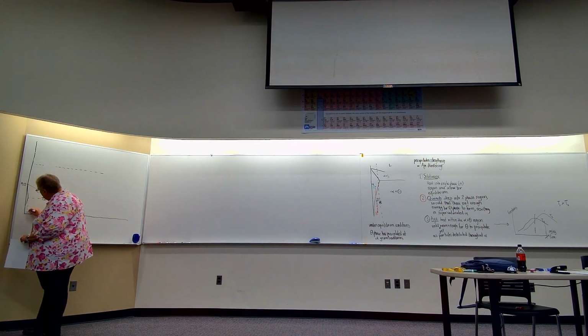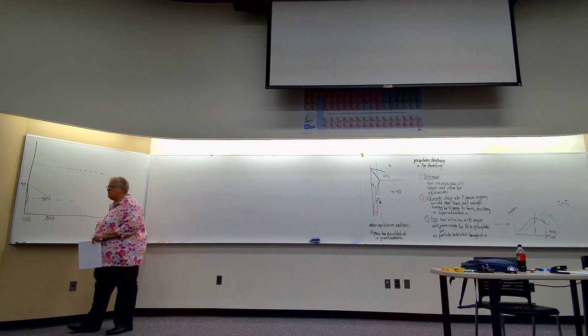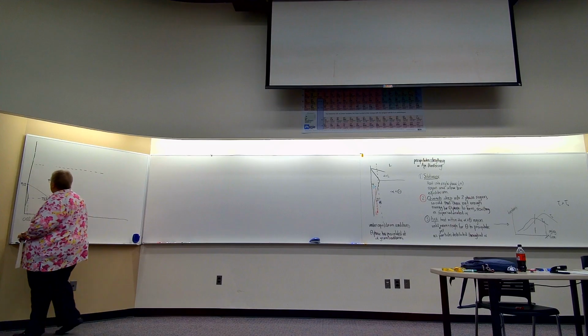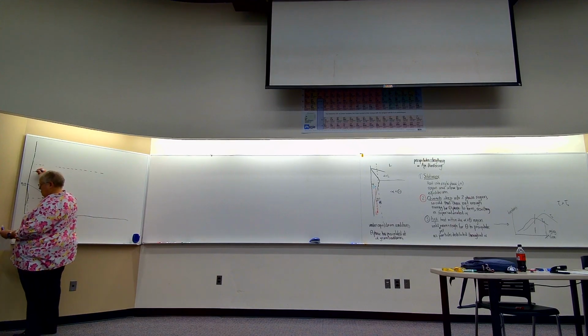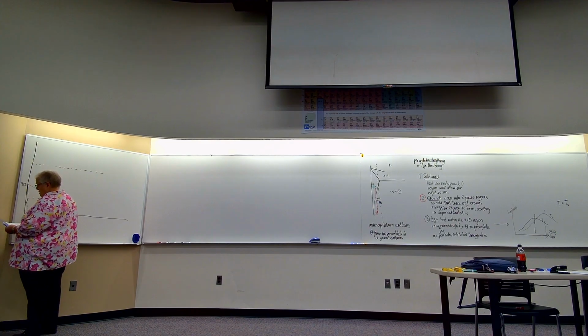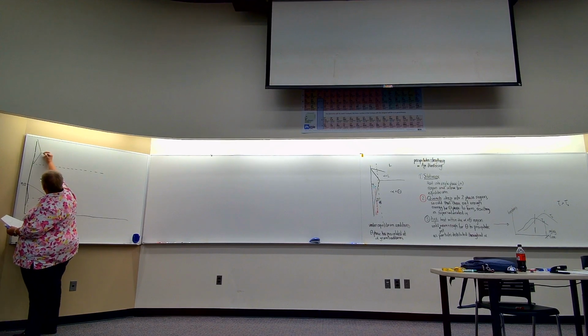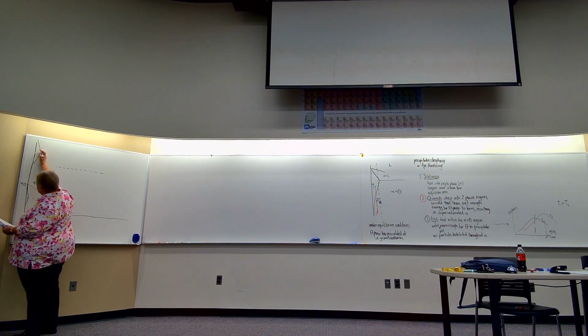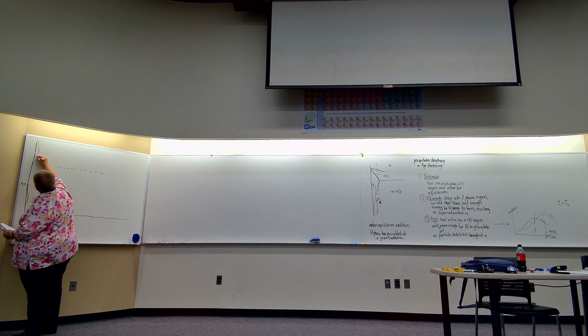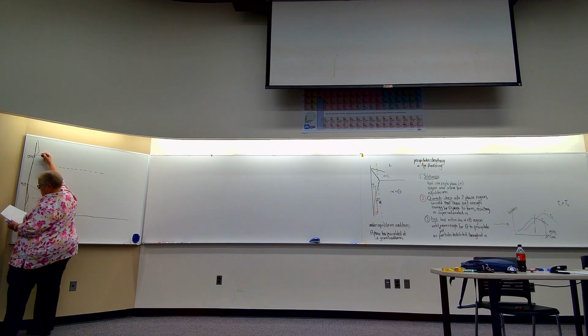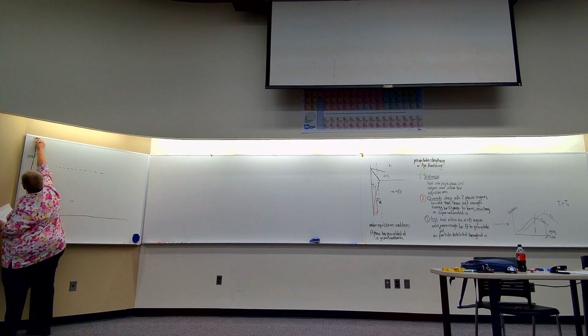This point right here, I always call 0.02. I've seen 0.022, 0.025. Again, it's really not going to change your answers too much. Okay, so then at 1148 C, we go up, down again. And this is maybe not quite that far. 4.3 and 1538.